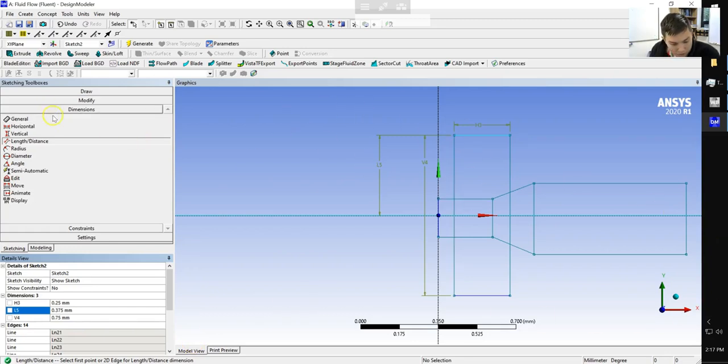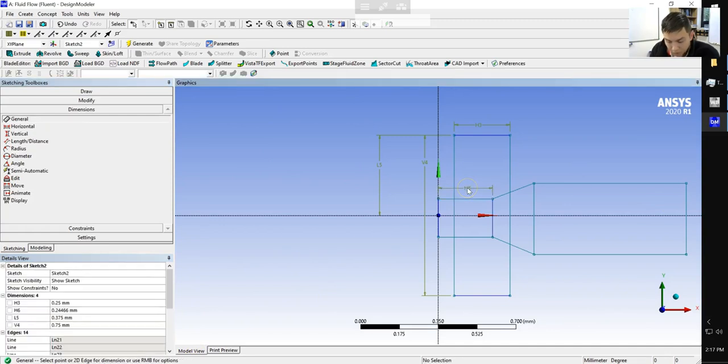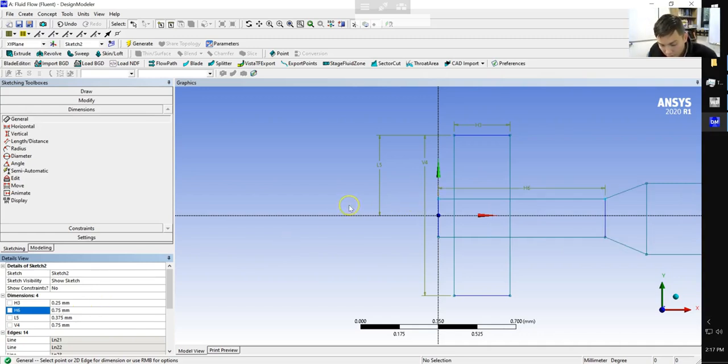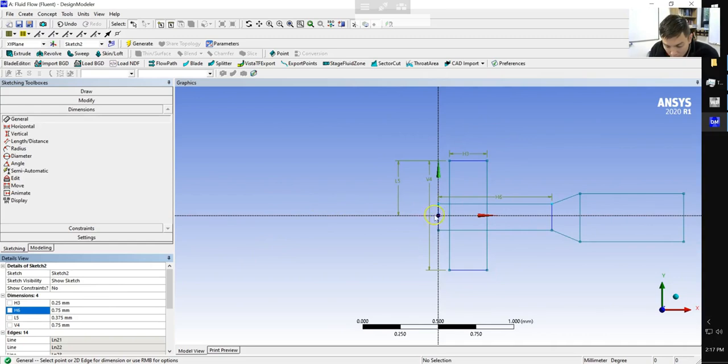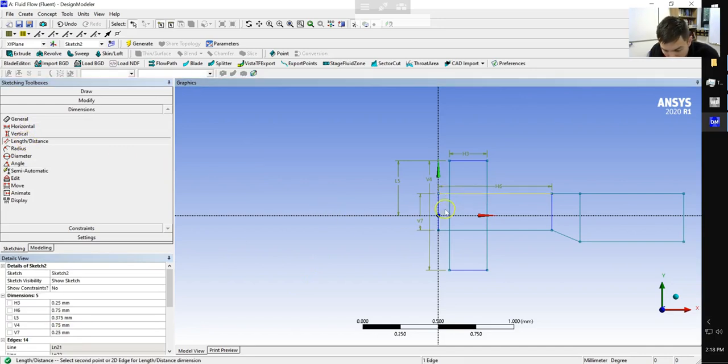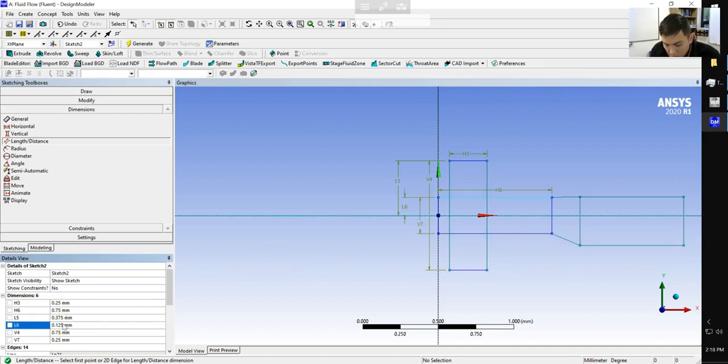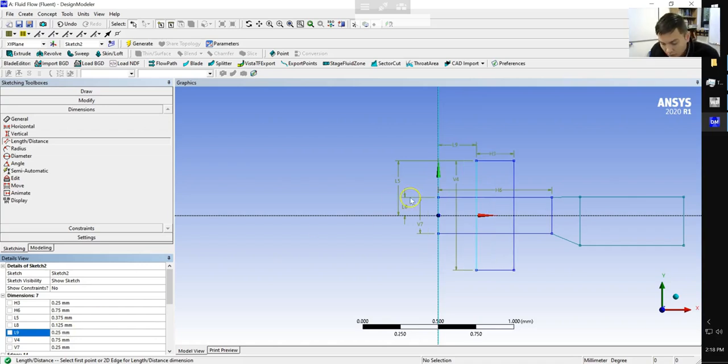When we go ahead and set this dimension next, this is also the length of our horizontal rectangle. It is also going to have a distance of 0.75, which nicely pushes everything out. And our height is going to be 0.25, with a distance to the x-axis of half of that, which would be 0.125. Our distance to the vertical rectangle is going to be 0.25. So now we can nicely see our plus sign showing up here.